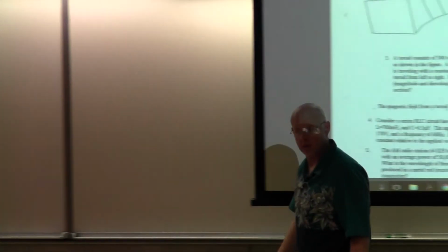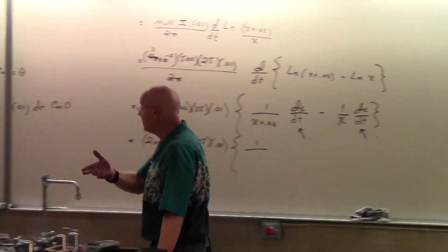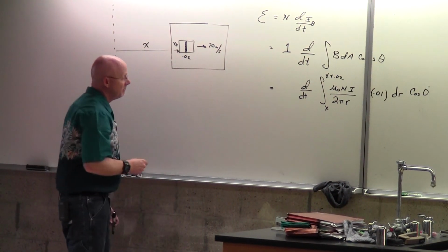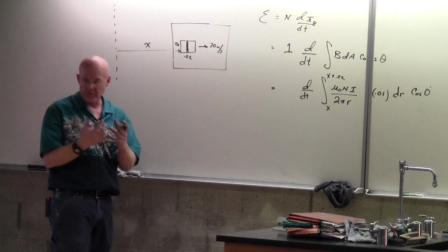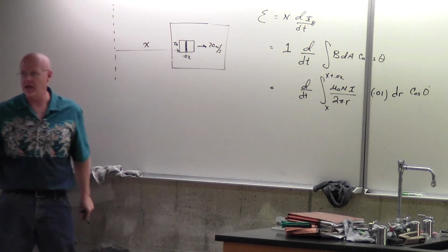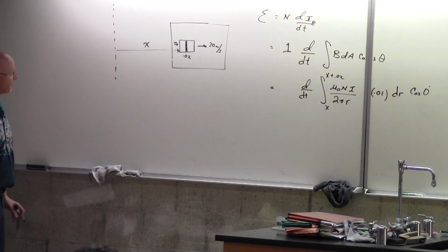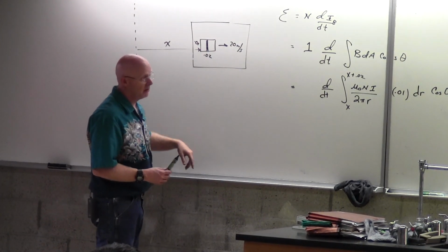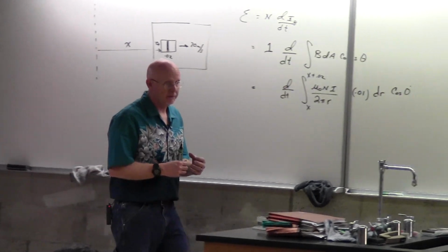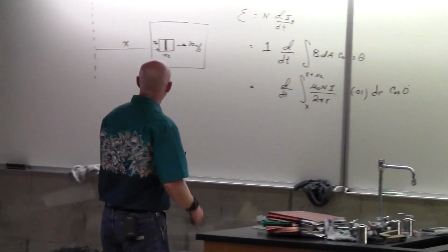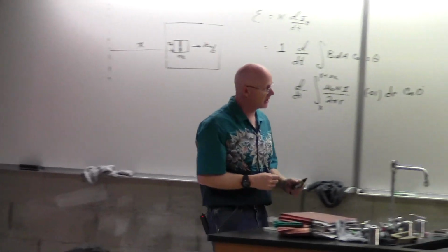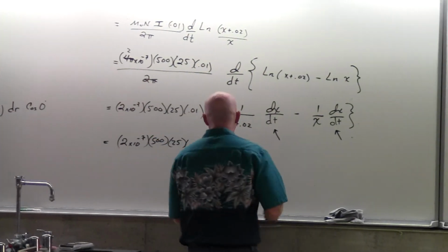Right? And just be careful here with our details. X is measured from this front edge the way we did it. Makes me think we probably should have done the middle of it, but that's not the way I set it up. But the middle of this rectangle, at the middle of the cross section, would be 7.5 to here. So coming back would be 6.5.